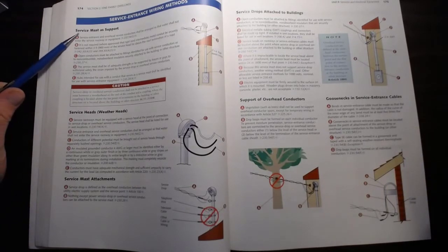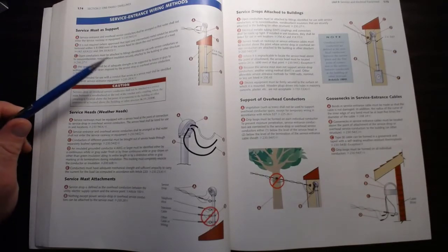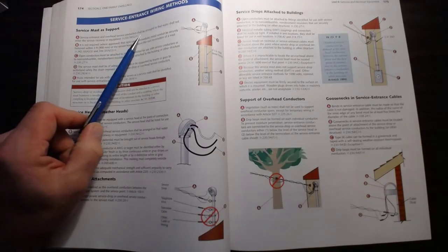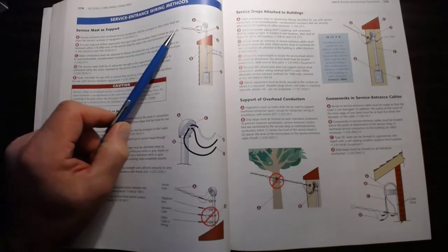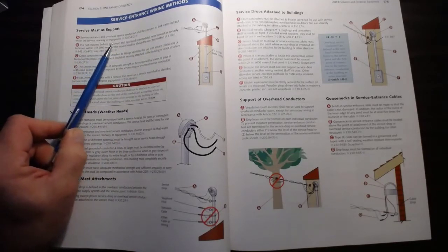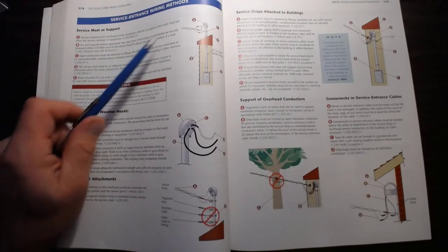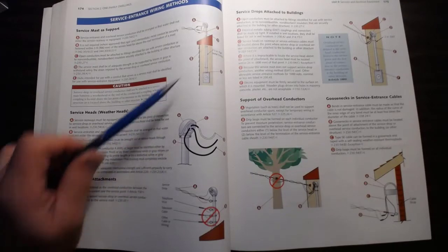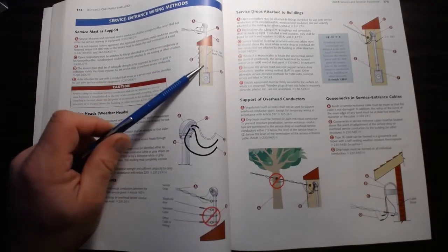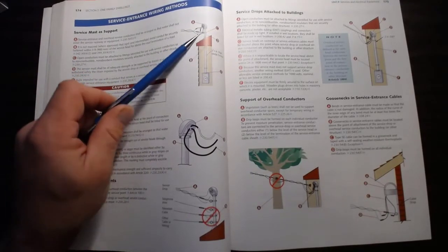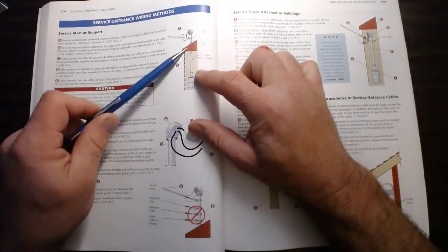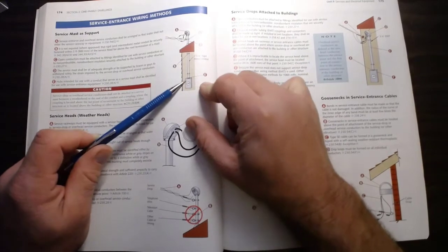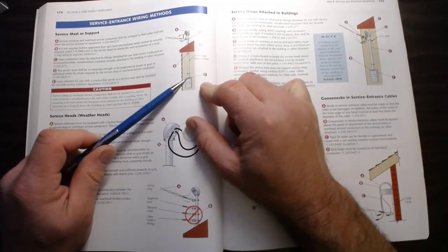When we talk about the service mast as support, we're looking at the service entrance and overhead service conductors shall be arranged so that water shall not enter the raceway or equipment. So we have to have a weatherhead on top. Now, the way this is designed is you would buy one to two sections of the galvanized rigid conduit, and you're going to use the threaded end in a hub that then screws to the top of the panel.